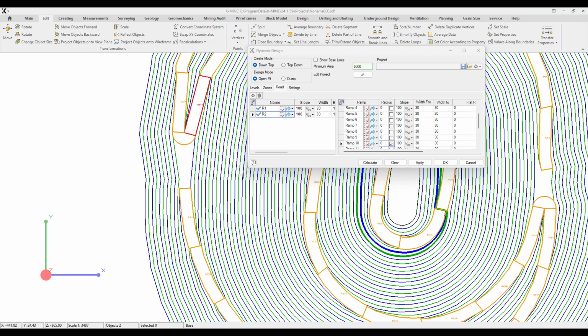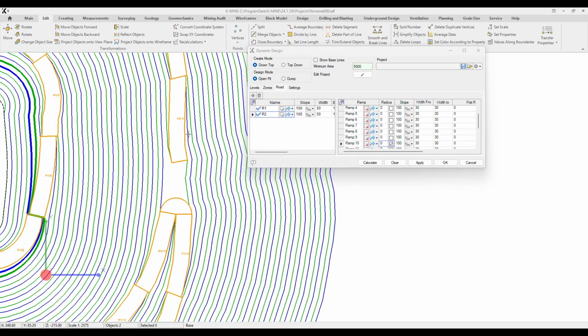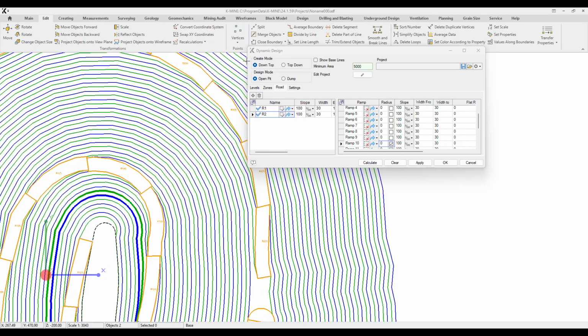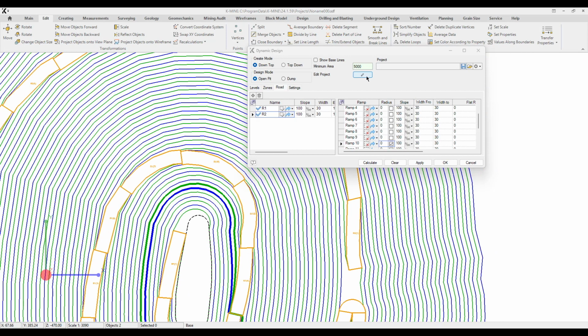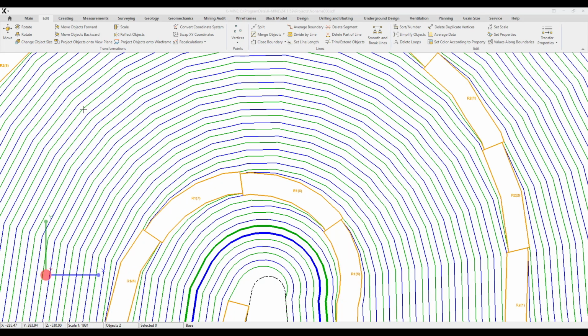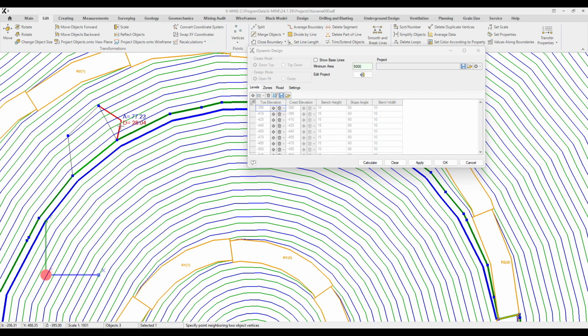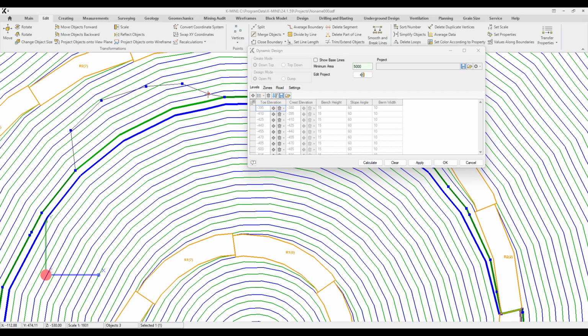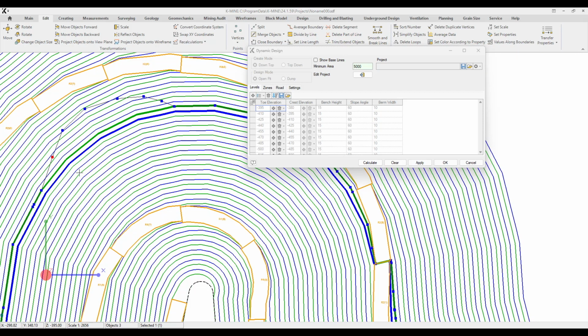Now, with just one click, we can add a horizontal road between the switchbacks, or the terminated roads located on the same level. If we need to get involved in the automatic creation process at a specific point or level, we can reconfigure any design line, add, move, or delete vertices, smooth lines, and run any other commands available in the K-Mine environment. That's the benefit of having a package product. We work in one plugin and use the features of other plugins.